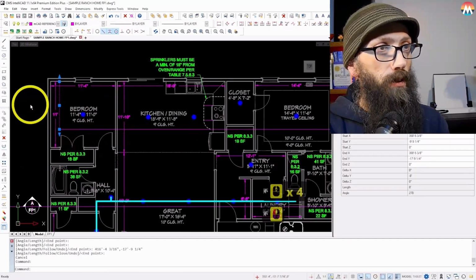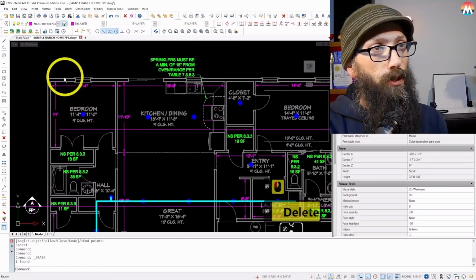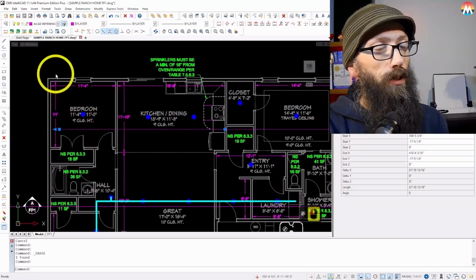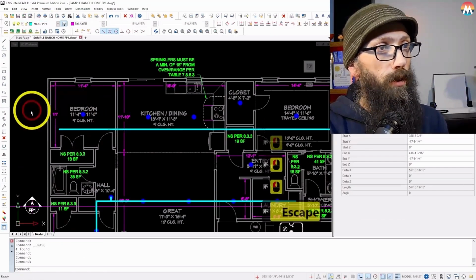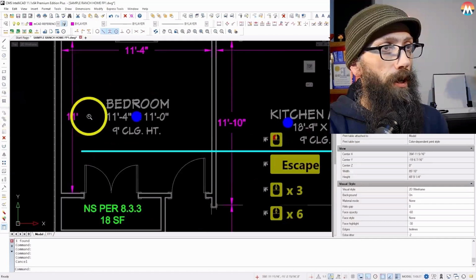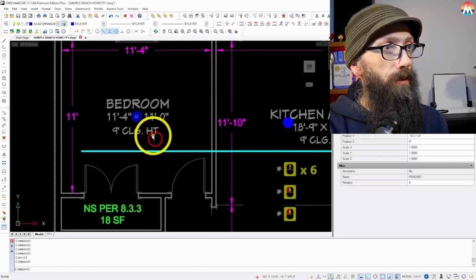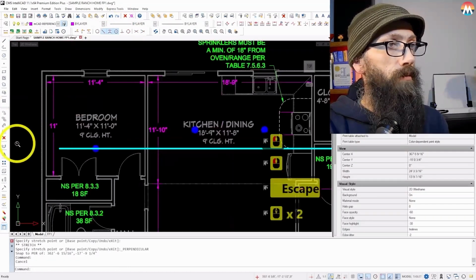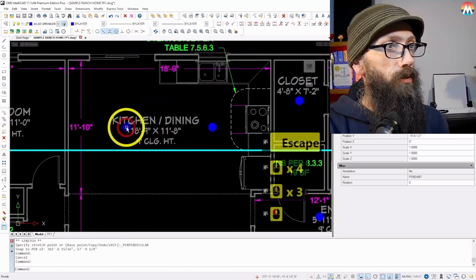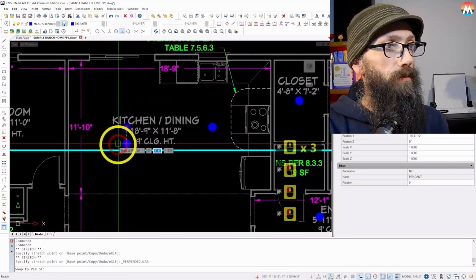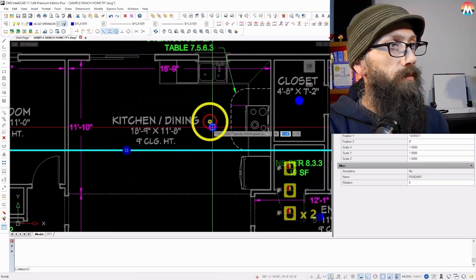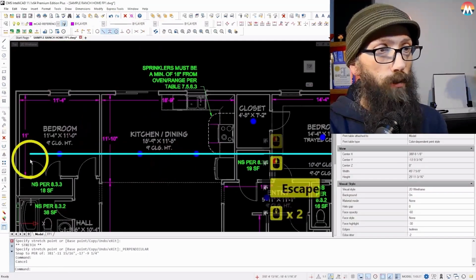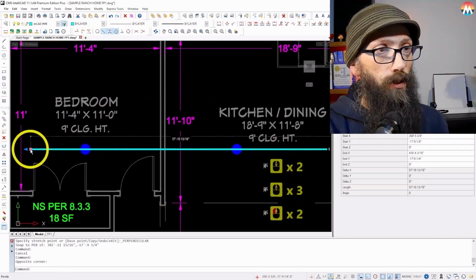I'm going to delete that. So I just drew a line 8 feet down and then straight across the building. And I'm going to now select this and make that a pipe. And now I'm going to select my head and go perpendicular. Yeah, I'm going to select these and do it as well. I'm grabbing the grip, using this. When you grab the grip and move them, it automatically goes into the stretch command.